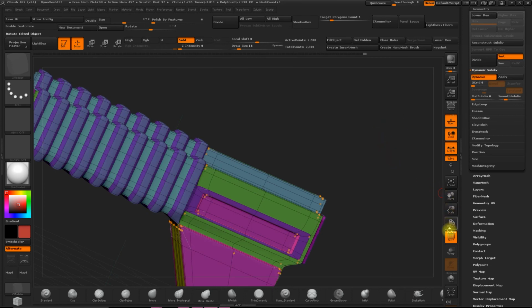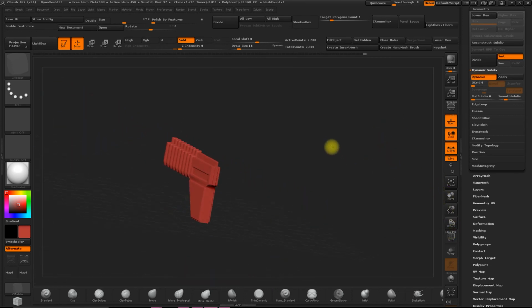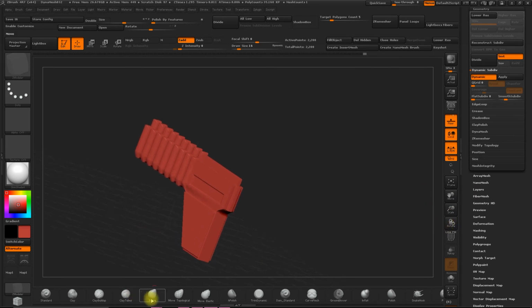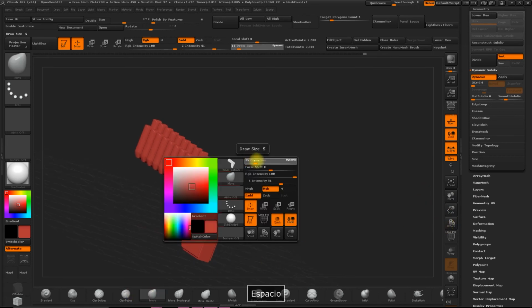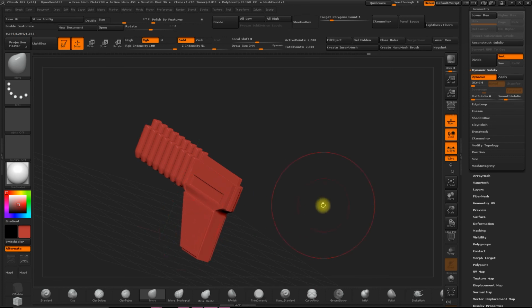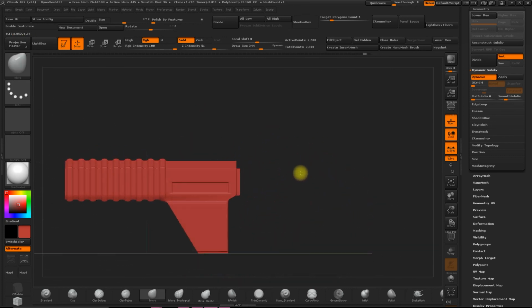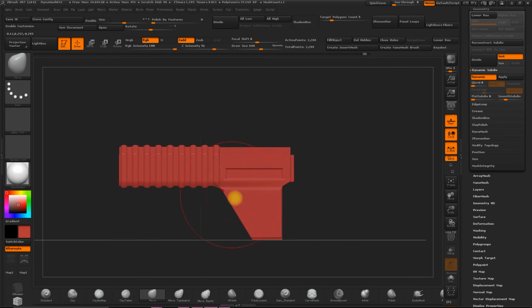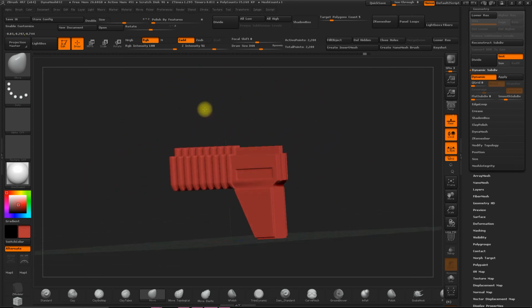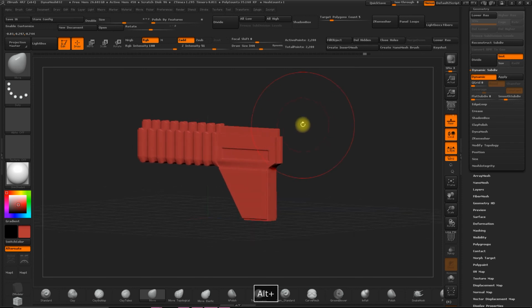We'll hit dynamic and we can see the shape our model is taking. Later, obviously, we can use any element and this is completely modifiable. We can stretch, we can modify any point. Anyway, you could do whatever you want. So we could get this element and transform it into a Dynamesh and continue working with it.